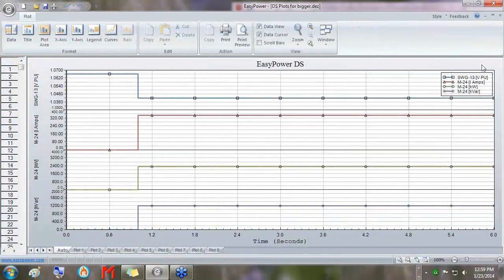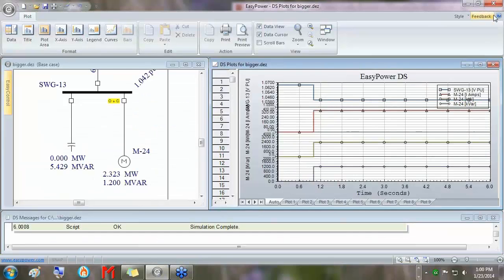notice that it's exactly what we have. We have no dynamics information. We see no rounded curves or anything because all we did was run steady state for 1 second and then throw the load of the motor back on, and we step up into that condition and continue on. So we went from off-load to an on-load condition. And so you can do any of these types of switching actions inside the dynamic stability focus without adding any dynamic stability data at all in any of your equipment.